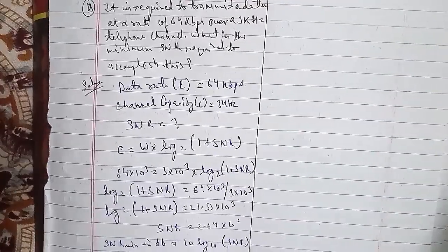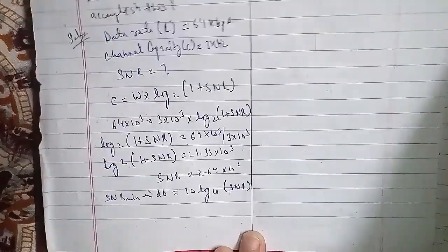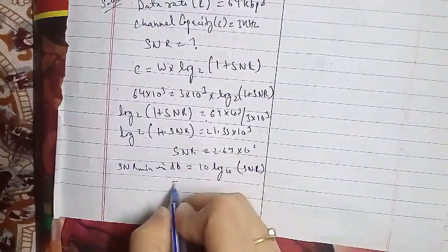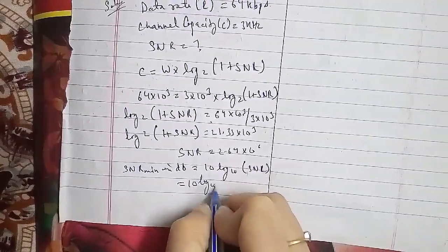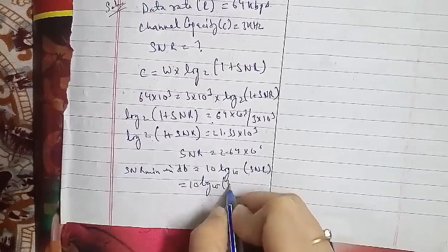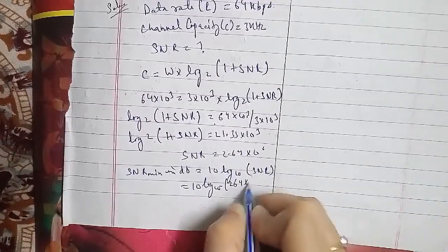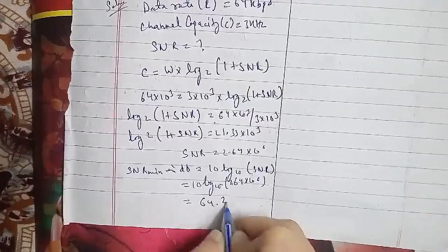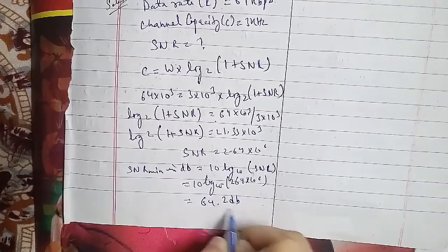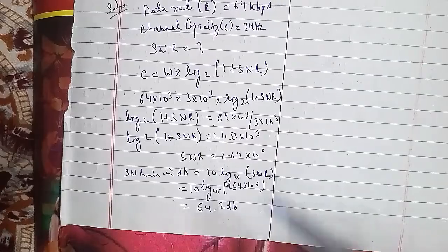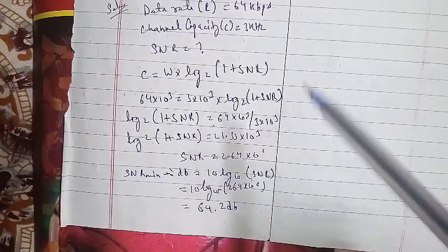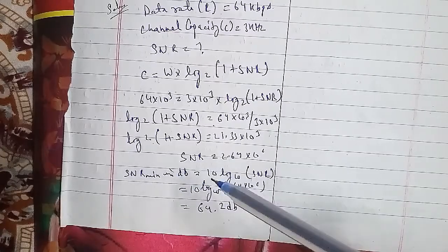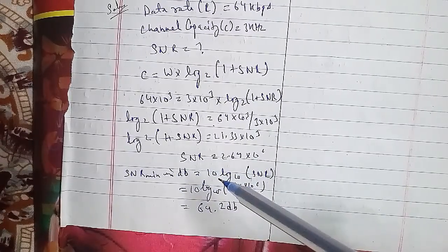Signal attenuation increases as a function of frequency, and in general the signal gets distorted because different frequency components undergo different attenuation and different delays as well. The problems of attenuation are: first, the received signal strength is reduced and the receiver circuitry may not be able to detect the signal. Second, the received signal strength must be sufficiently higher than the noise. Third, attenuation is an increasing function of frequency.